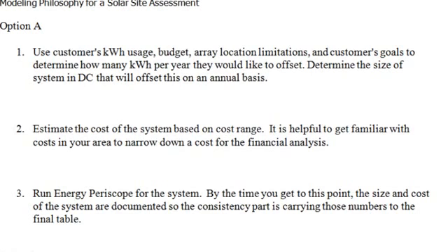And so what you can do when you're doing this option for site assessment and system sizing, and this is really for site assessing a system, is to say, okay, based upon $7,000 in your location that you have available on this roof, you could probably do, looks like, a 2 kilowatt system. And now you could give them a base analysis as step 2, which is then what you put into the PV site assessor. Hey, based upon a 2 kilowatt system, that's the thing that we want to have happen, and what we want to do is go over that basis there.